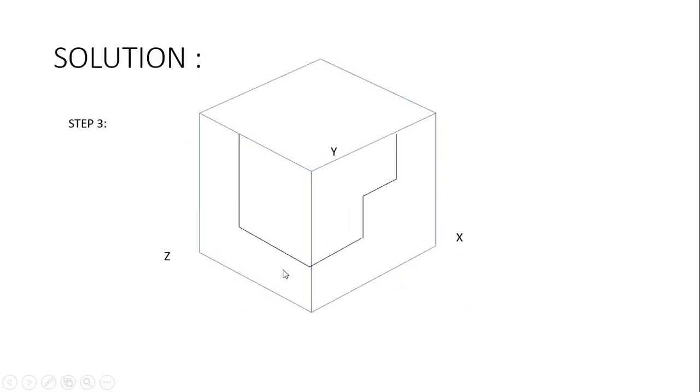So now we have to sketch the left side view in 3D projection, isometric projection. So draw a vertical line for 60 mm, 20 mm, and this is 30 mm, and this is said to be 40 mm. So now the left side view is drawn, and the front view is also partially constructed, and the remaining one is the top view.